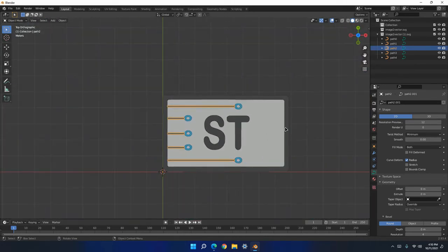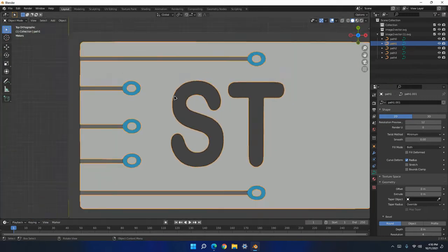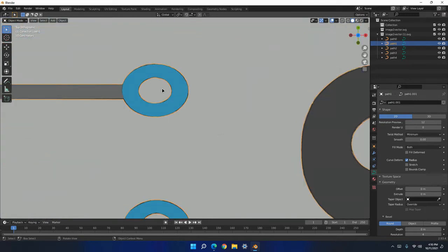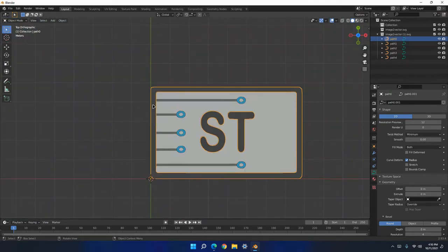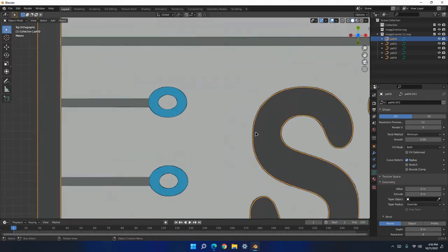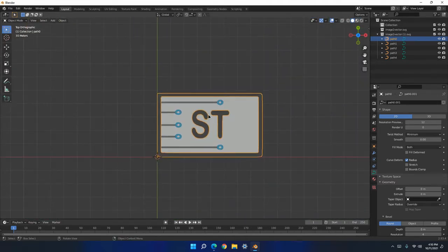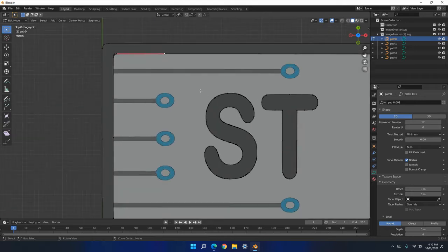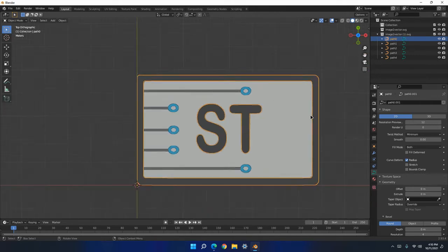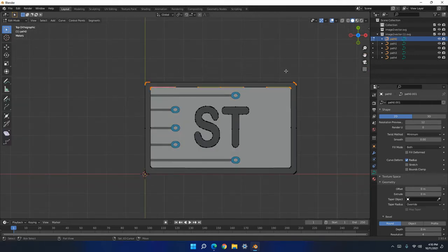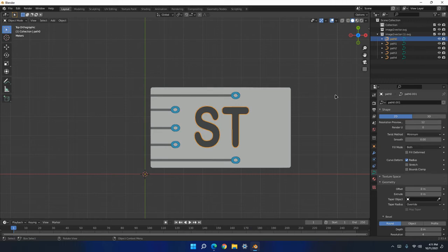So now you might be wondering, if you select this outside, why is the text and this stuff also outlined? Well, yeah, the text outlined. So now to fix this, if you want to separate it, just hit tab, select all of these, copy it, and then hit tab again, but this time instead select these, hold shift, and then delete, dissolve, and then you want to come back to view mode, and then paste.